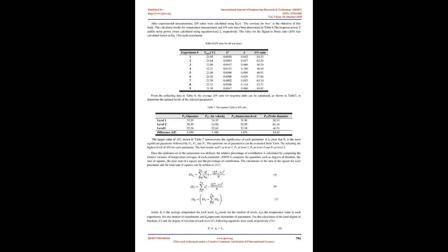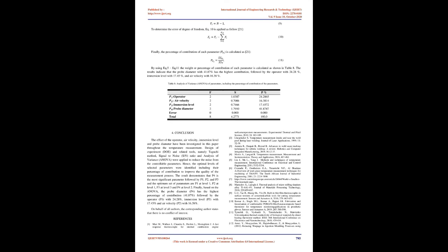For the calculation of thermistor constants A, B, and C, the temperature was measured 3 times at 2 different conditions. The evaluated coefficients using EQ.4 are presented in Table 4. The accuracy of calculations and measurements was validated, and the maximum overall error for the temperature of 25 degrees Celsius was measured as 0.0007%, which is negligible.